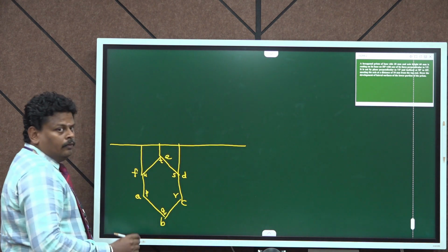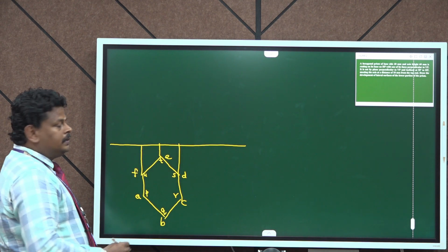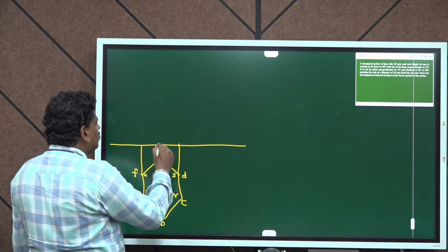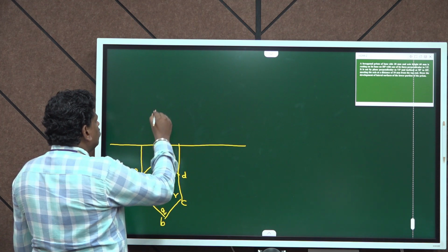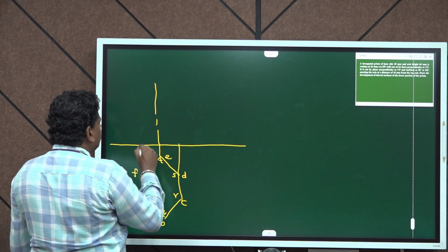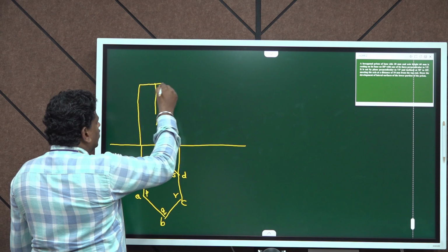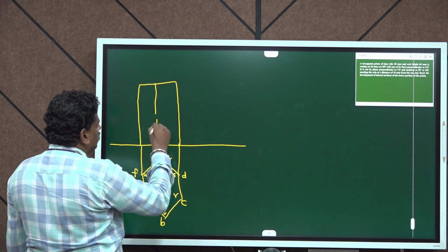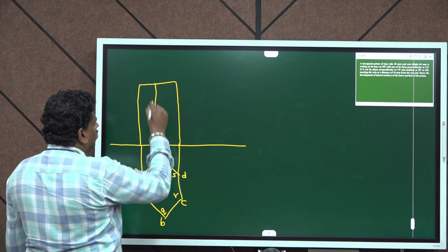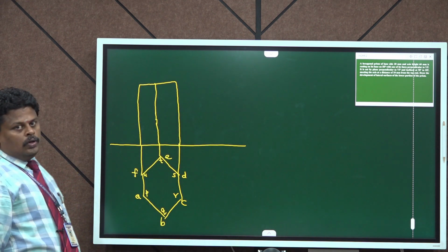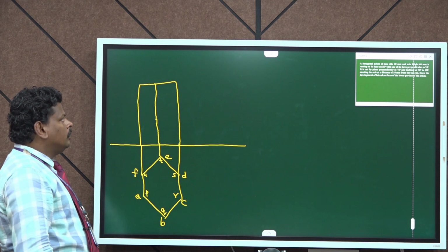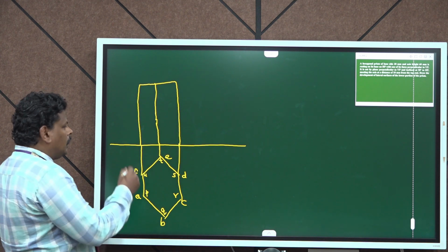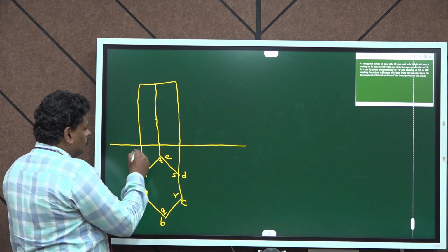You can draw the front view. The axis height is given to be 60 mm. We can draw the axis height of 60 mm. Here the axis height is coinciding with the edge of the prism, so we will get a continuous line. We can mark the points in the front view.